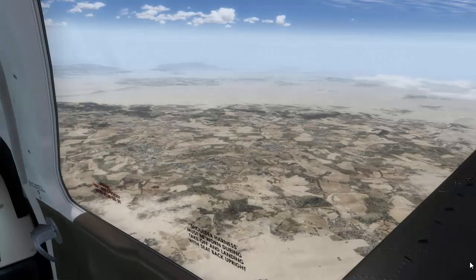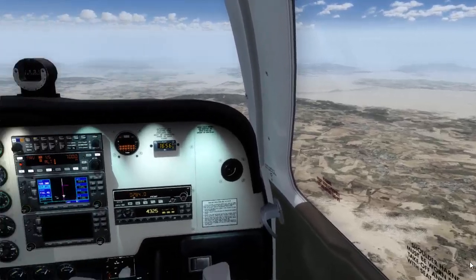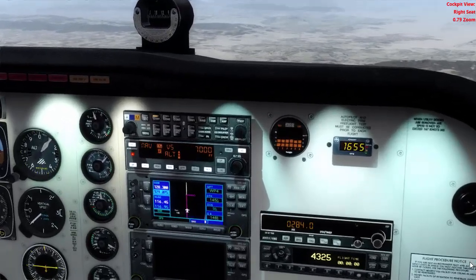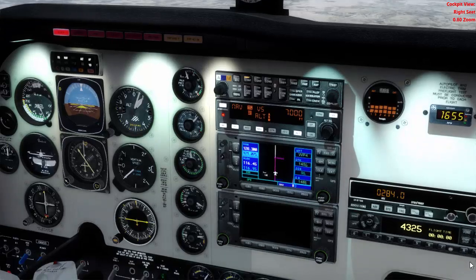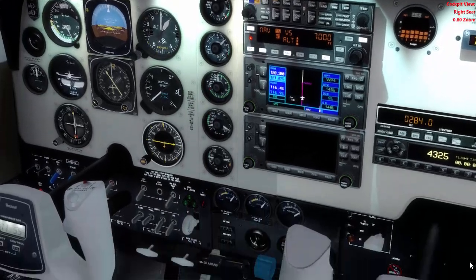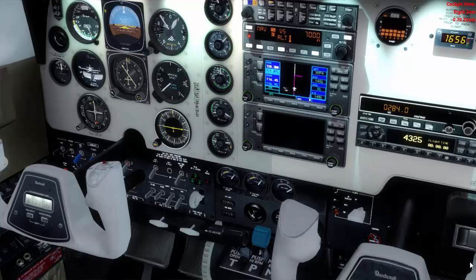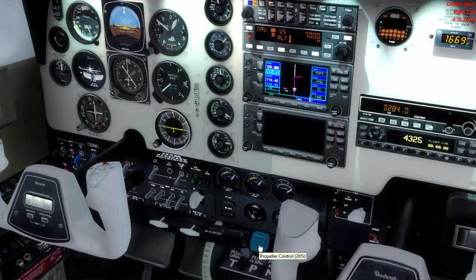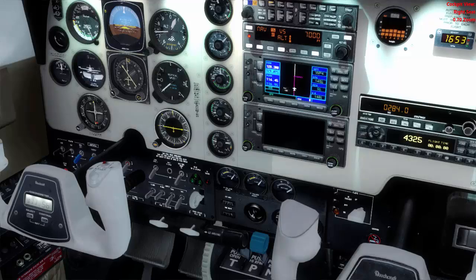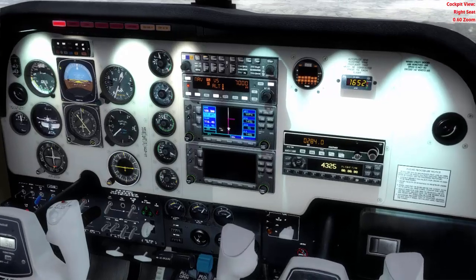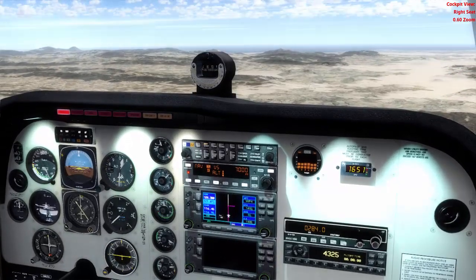When we descend and follow the STAR chart and the IAC chart, the instrument approach chart, we will need a lot of energy, because we will need to be focused and concentrate on the approach, and we will need to understand several things. So we'll do that. And right now, we will reduce a bit the blue lever, because we don't want the speed to increase as we are descending, and we are also reducing a bit the black lever, because we want to cut more of the speed of our engine. We don't want so much speed. Remember, the aircraft has its weight, and is descending.